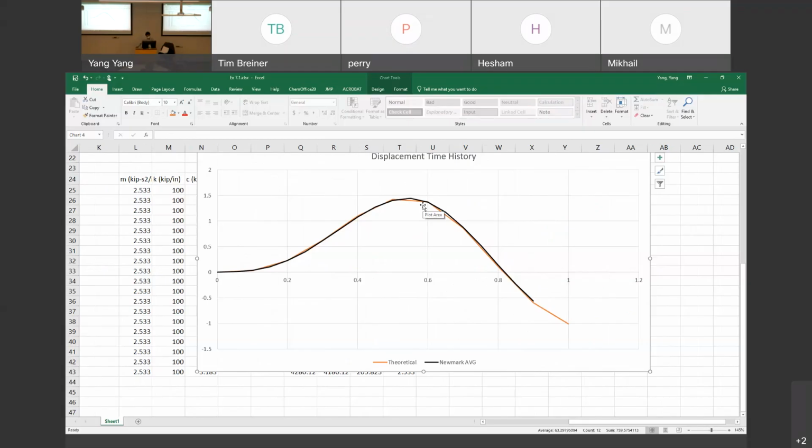So typically, for both methods, the central difference method or the numerical method, if you use a finer time step here, you will get a more accurate result. But a finer or smaller time step typically produces more data, and the calculation will be slower. There will be some compromise of the computational effort or time here.